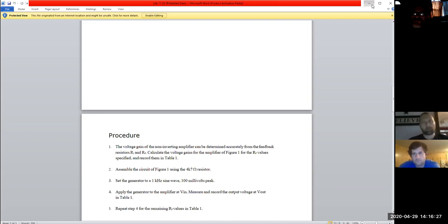That's the thing to remember with these. What's at the heart here? Really don't think of them like digital input voltages, like plus 5 volts and ground. The VCC and VEE on those pins are still technically bias voltages. So we're still biasing the device and the amplifier internal to it.